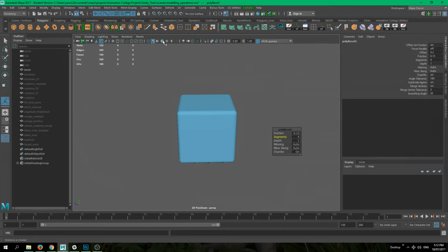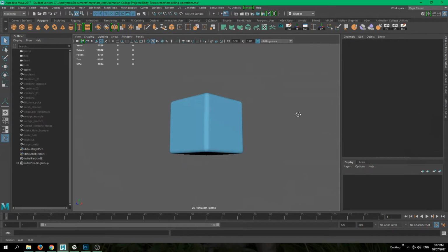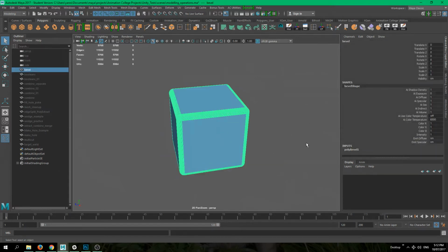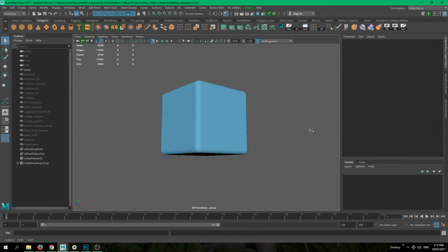And we can also see, if we turn on our wireframe, how much geometry we're adding. So at the moment it only goes to 12, but you can always override this number and put 30, for example. And you will see that we're getting really dense type of geometry, and we can uncheck our wireframe. But to be honest, it looks almost the same. So I wouldn't really recommend to go that high unless you're trying to achieve something specific.